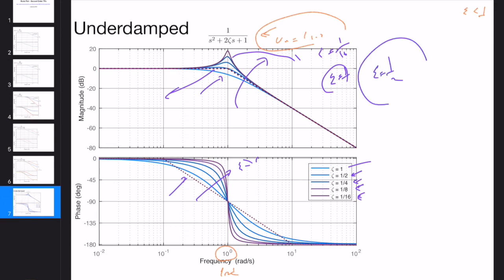Okay, so this is kind of interesting because indeed, if we do the maths, basically take the derivative with respect to psi and try to find the best possible approximate response, we will see that when psi is equal to 1 over square root of 2, the error between the actual Bode plot and the approximate Bode plot will be minimal. Okay, but for the phase case, the best approximation seems to be still the critical damp case.